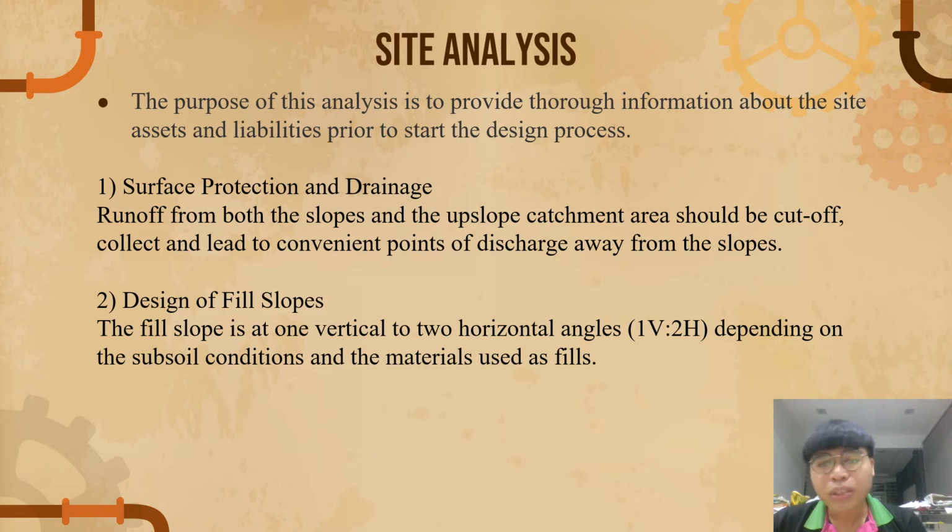Now I'll talk about the site analysis. The purpose of this analysis is to provide thorough information about the site access and liabilities prior to starting the design process. First is surface protection and drainage. Runoff from both the slopes and the upslope catchment area should be cut off, collected, and led to convenient points of discharge away from the slope.